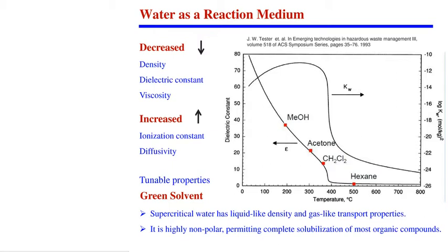So what we see is that water is a polar compound at ambient condition. When you start heating at high temperature under pressure, its dielectric constant goes down, that means polarity is going down, it's becoming more non-polar, and we know the fundamental is like dissolves like. So because of the drop in dielectric constant, organic materials are dissolved in water. So in a crux, I am saying water, not the steam.